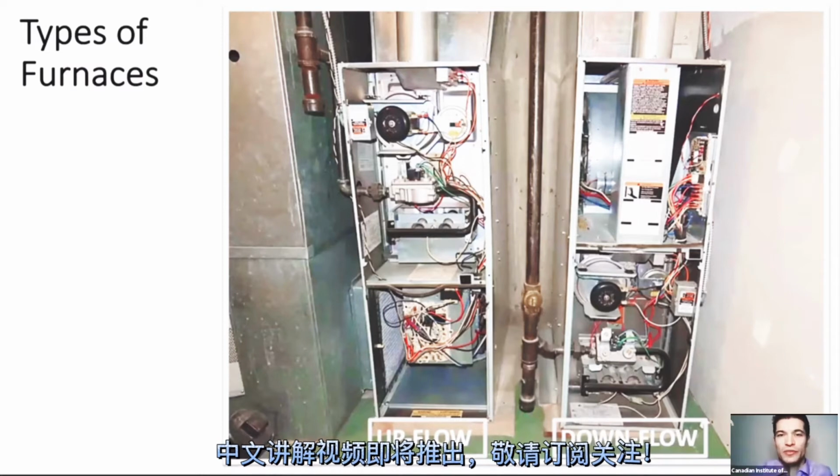Make a quick note here, Sam, just about the inspection process, guys. When you take your photos of the furnace and take off the upper and lower furnace cabinets, you want to be checking for a few things. First off, you want to see if there's a filter installed, and make sure the filter is installed properly. Generally they'll have airflow written on it with an arrow pointing towards it. The easiest way I tell my clients is to make sure the arrow points towards the furnace, because sometimes you may have a different orientation. A lot of times, looking at the filter size to make sure it's sized accordingly, or its actual state, if it's extremely dirty, will tell you a lot about the maintenance of the house.